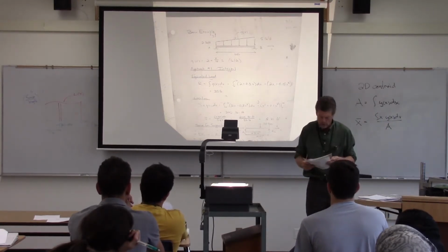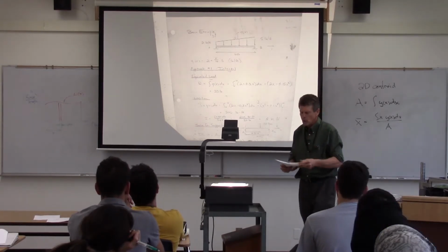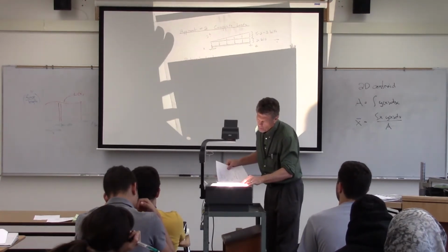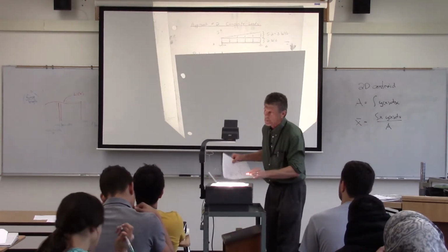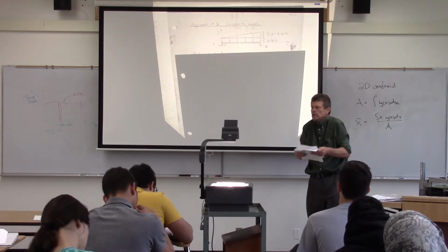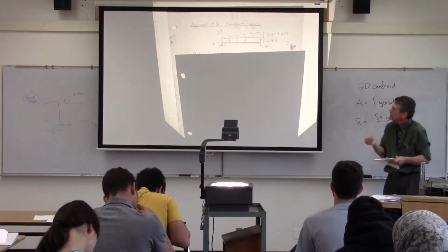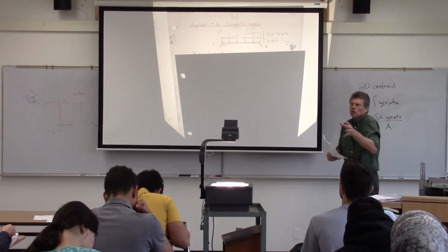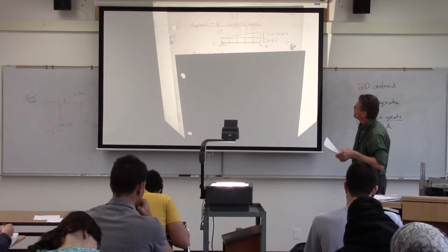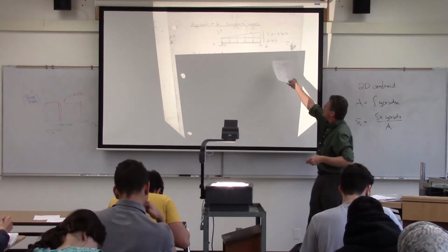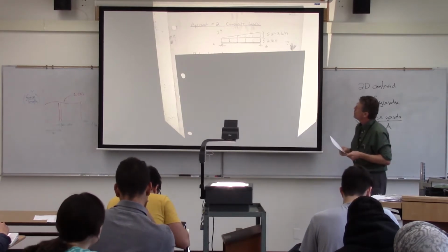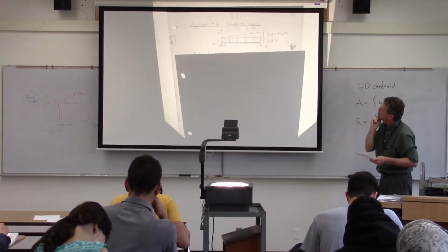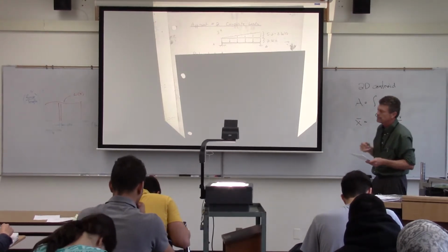What we're going to look at next here is the simpler approach, what we learned last week, where we can break it up into composite pieces and take advantage of the discrete formulation of finding the centroid via two known composites and just simply using a table method. So what we can do is break it up into a rectangular and a triangular area like so, noting that this leg here will be 2, and then the increase of that leg, which creates the leg of the triangle, of 3.